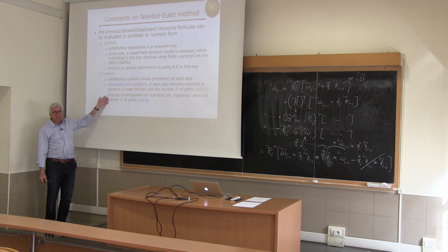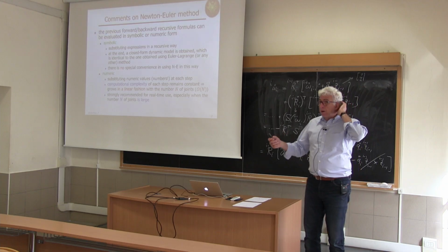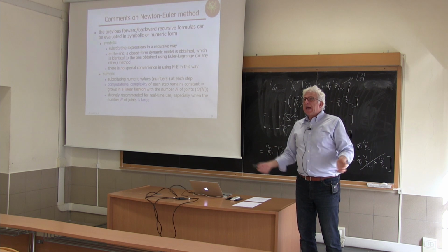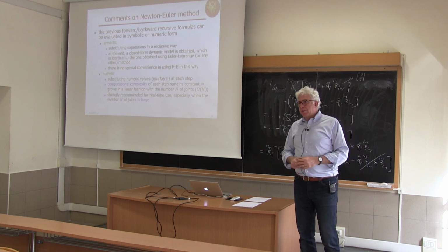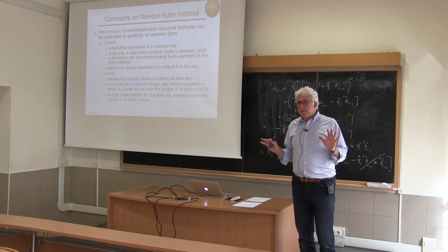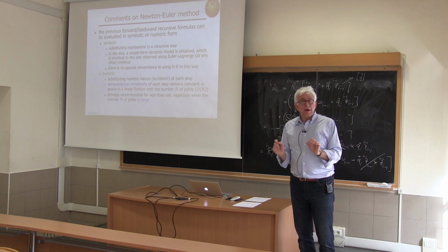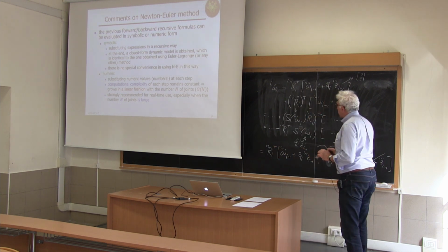And in fact, the nice thing is that if you do this, you have general formulas. You don't have to specialize this for your particular robot, as opposed to the Lagrange method where you need to do the computation symbolically for the specific robot, and then later on you may plug in numbers. But first you have to derive the model. Here, you don't have to derive the model explicitly. You just use this tool for computation, numerically. And this is a powerful, very powerful result.